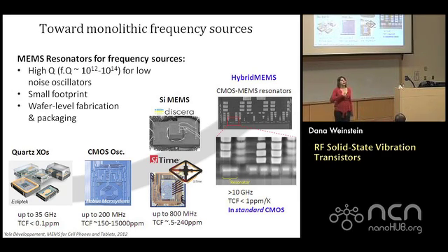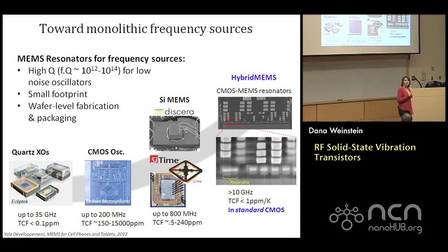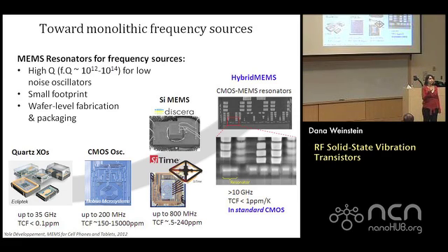And we want to scale to very high frequencies of operation, where bandwidths are much larger, where there's interesting new applications at multi-gigahertz frequencies. Now, we can see even in the consumer market where MEMS has come in and stepped in to try and get the best of both of these worlds. But what's out there is silicon MEMS resonators that are basically flexural beams, cantilevers or clamped beams, which are driven and sensed using air gap capacitors.